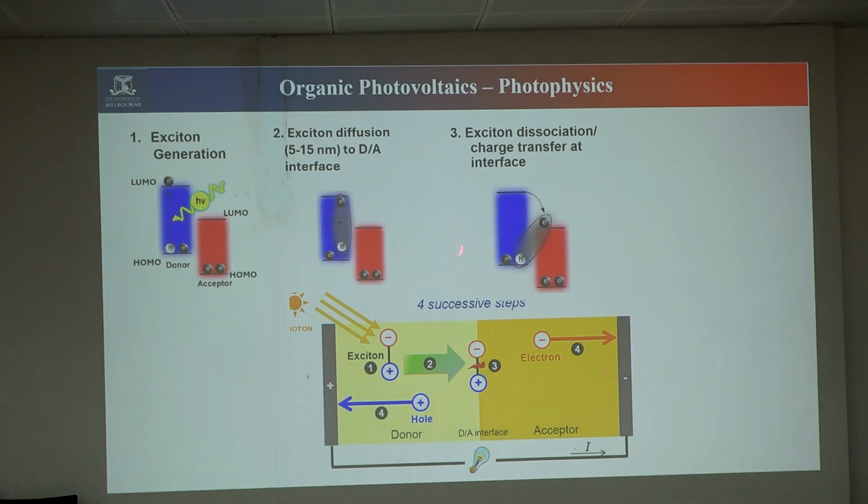So this dissociation is very important to get the charge separated. Next, after the separation, the electron travels to the charge extraction, where the electrode is connected. The electron acceptor is called the cathode, and after that the hole goes back and goes to the anode. Then finally it will go out as a useful current. This is the overall process of what's happening in the organic solar cell.